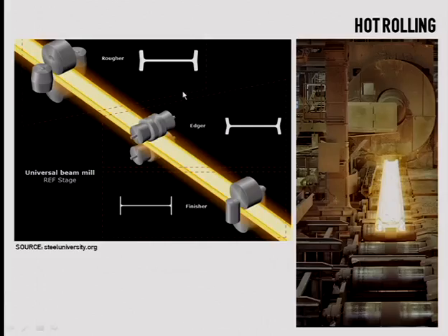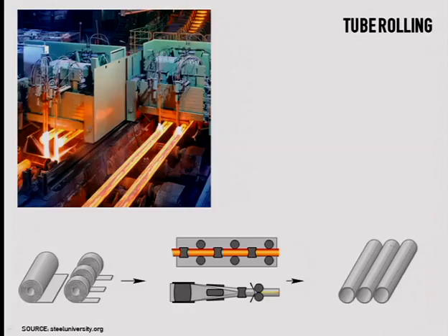And I can show you in another slide that this happens at least in 3 phases. It's even like the same happens when you have a CNC. First, there is always a first rough pass. So you tend to get this shape with these 3 rollers, just the first rough pass. Then there is the edger, just a refinement of the edges, and then the finisher. So in these 3 steps, I'm able to get that type of product. You see here the corresponding image to that diagram.